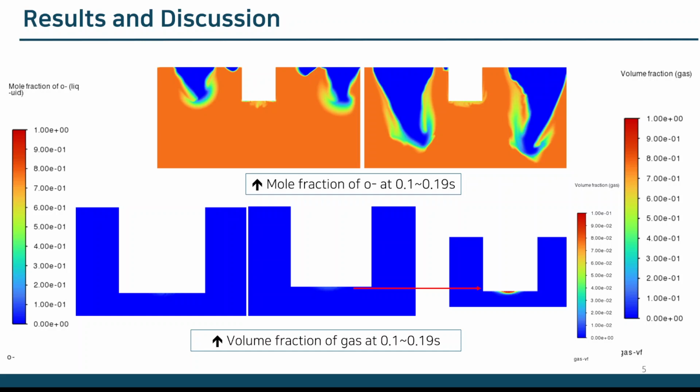Henceforth, I'm going to try not to use modules that are initially given in the Fluent, but to code own governing equations, especially species transport equations, so that I can add migration flux term as an user-defined scalar in this model.